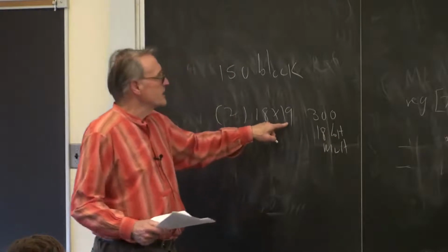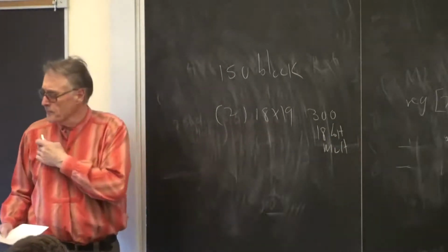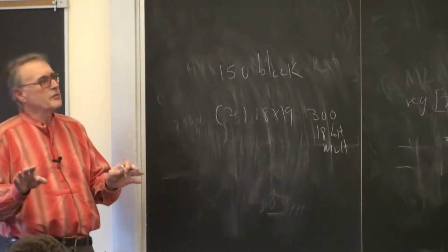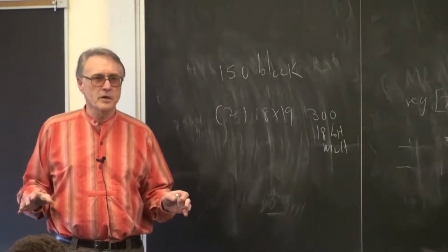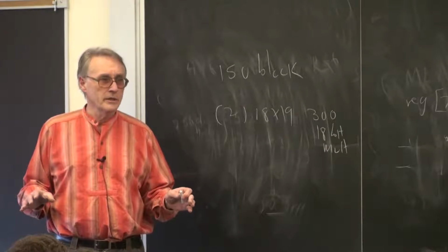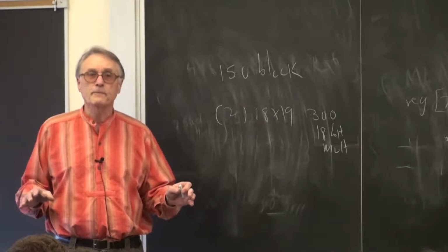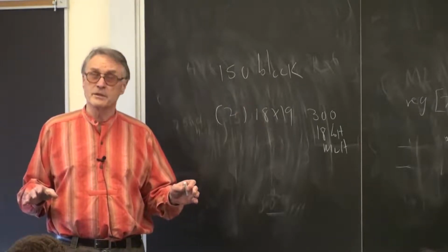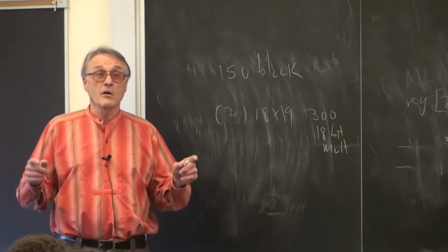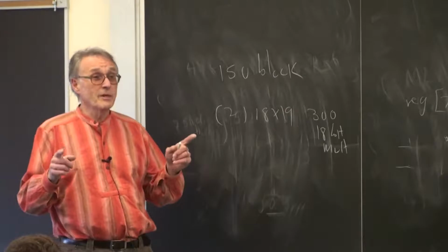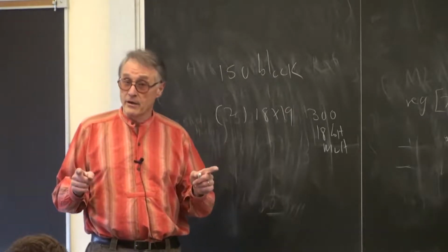The reason for this is slightly obscure, but not too obscure. Most finite impulse response filters are symmetric if they are linear phase, right? If you want linear phase, they have to be symmetric, I believe. And that means that there are always two samples that have to be multiplied by the same coefficient in an FIR.